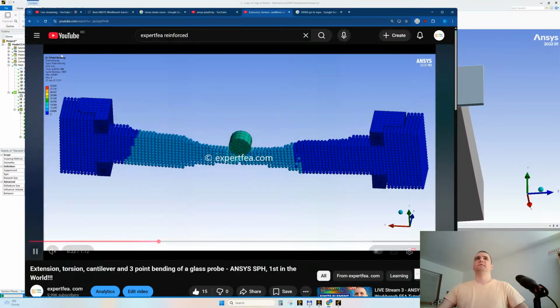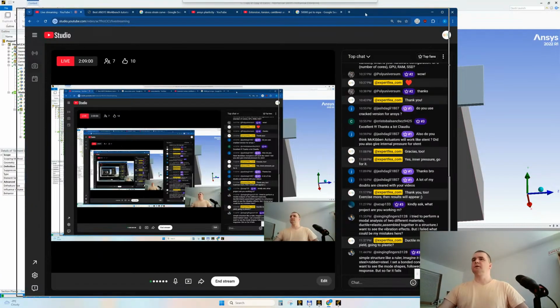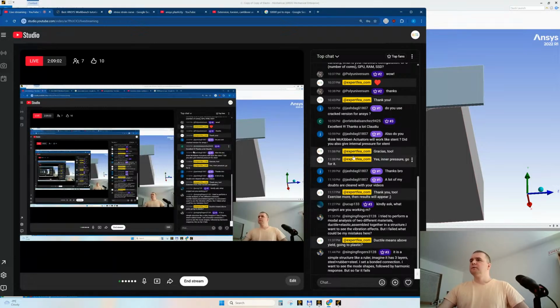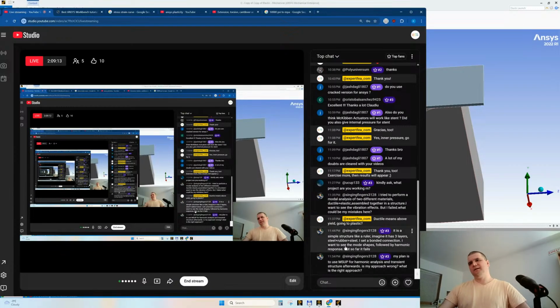Do we have any questions? I think we have. I try to perform, Doctor. It is a simple structure like a ruler. Imagine it has 3 layers: steel, rubber, steel. Rubber with modal, it's hyperelastic. I set a bonding connection. I want to see the mode shapes followed by harmonics, but so far it fails.